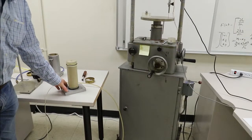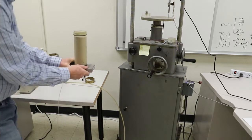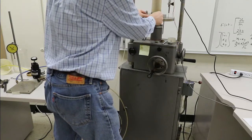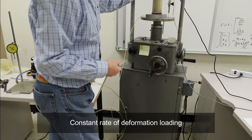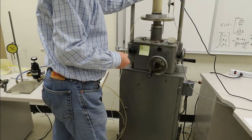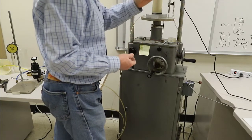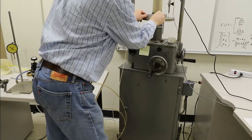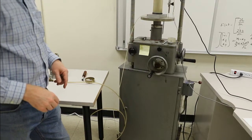So we're about ready to test the loose or low density triaxial specimen. Now we're going to pick it up and place it over here on the testing frame. This is a venerable old constant rate of deformation frame, which is actually really good for this sort of test. And I'm putting this extra top cap on that has a stainless steel ball bearing that fits in the top. That's going to be the interface between the sample and the load cell. We'll talk about that in a minute.